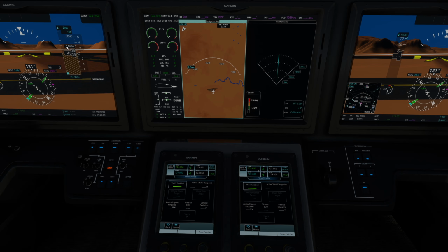But that works. It shows you everything. It just doesn't automatically start doing it. So essentially what you would have to do is you would have to control your speed, and in the Longitude with auto throttle, that's really easy. You can set the auto throttle to whatever speed you want while you descend and just let that control itself. And then what you would need to do is just track these carets, depending on where they fall on here, what vertical speed it tells you.